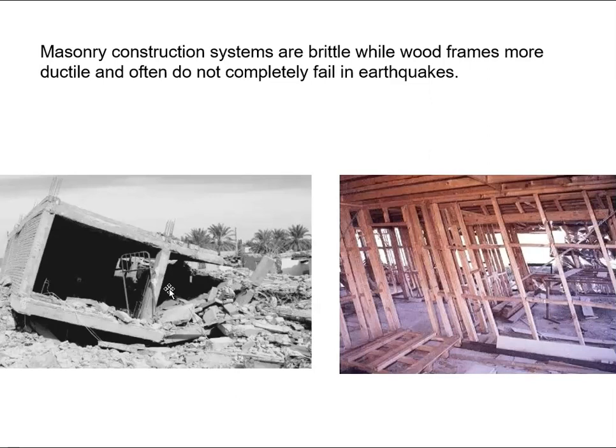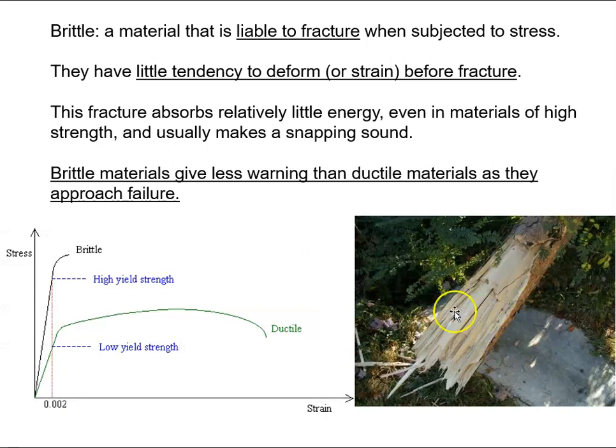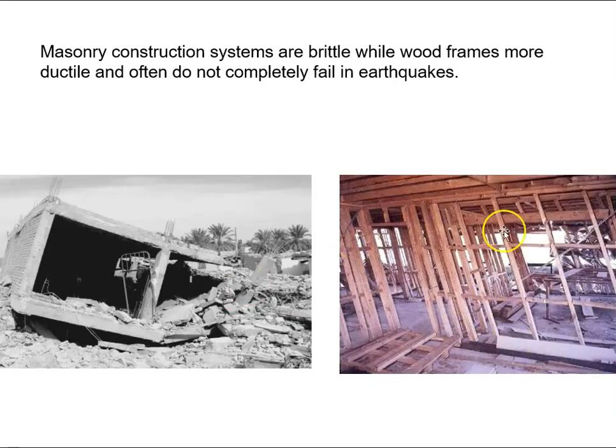Not quickly necessarily. Wood, however, while typically brittle by itself, when it's put together in a system is actually quite ductile. So a residential low-rise platform building is quite ductile, and in the case of an earthquake is one of the preferred systems to be in. So this building will never be the same again. Obviously, it'll have to come down. You can never repair that, but it's survivable. You get a lot more warning in a situation like this than you would here.